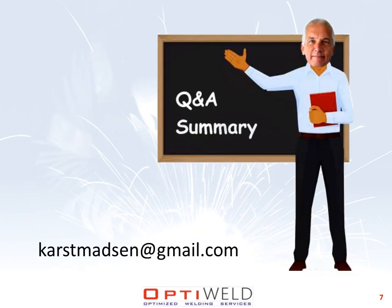So there you have it, folks, and I hope I've helped clarify visual inspection requirements to CSA W59 as it pertains to undercut and porosity evaluation. I think you've seen that for proper inspection to code requirements, you must be diligent in following these guidelines. Your inspection kit should include the proper gauges as well as a flashlight and maybe a magnifying glass to measure porosity. You will also need clear definition on whether Clause 11 or 12 is applicable, and in the case of Clause 12, we'll also need to know direction of primary stresses across each weld.